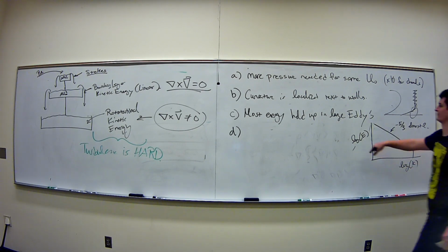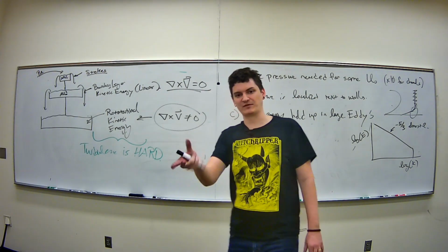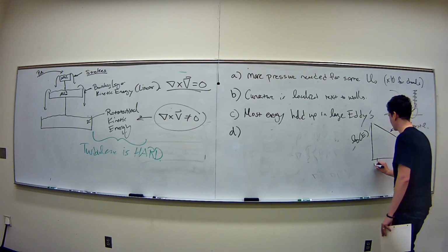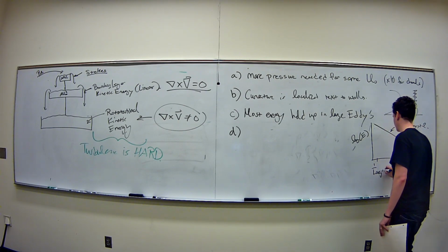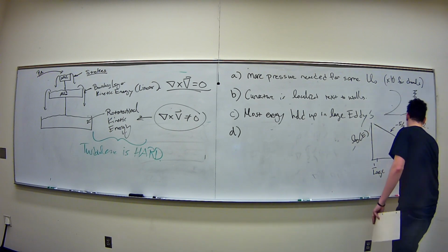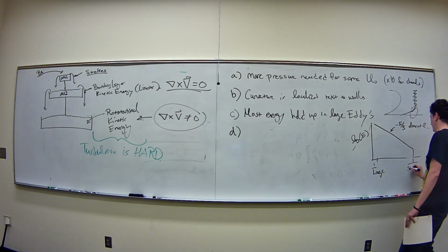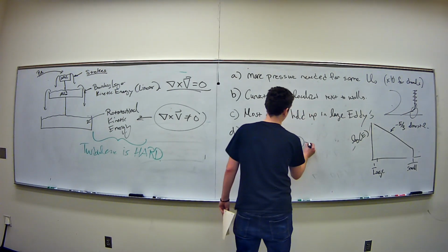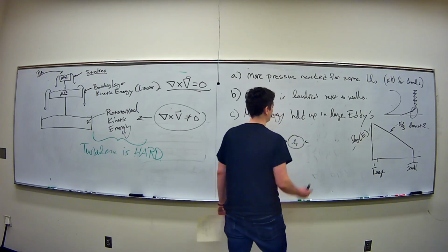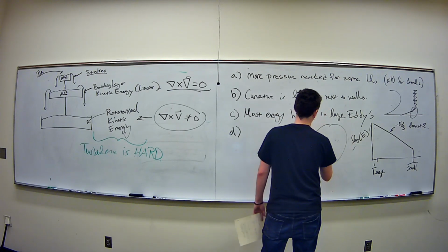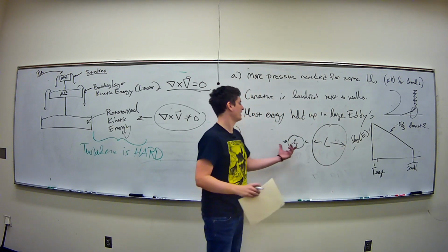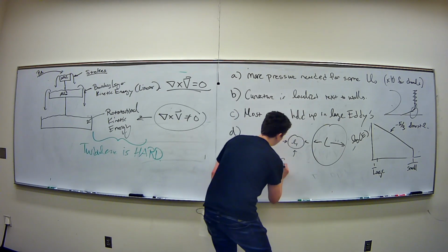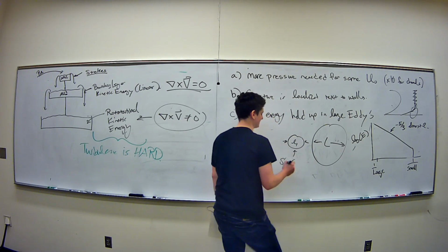This is the idea that for energies, if you look at just the size of these eddies rotating on a length scale basis, so K here is 1 over the length: large eddies certainly smaller K, and 1 over small eddies larger K. So a wave number being, say I have some domain here, I'll call it L1, then a big eddy here, capital L. If I think of a wave being like the smallest mode of a wave that could go through here, you could think of it as really a Fourier decomposition, right?